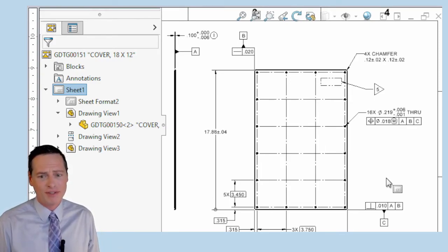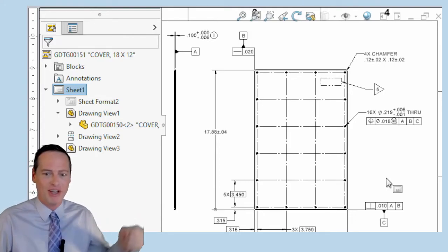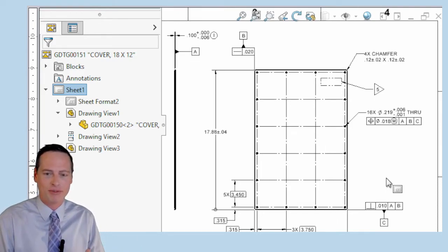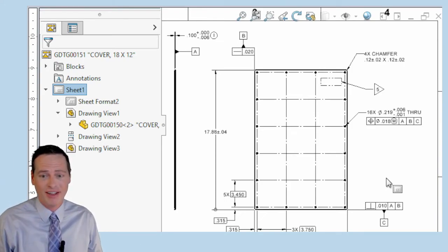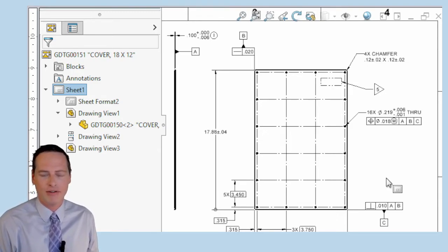This also asks a machinist to rough out the outer perimeter of the part, remove the part from the milling machine, put it back down on some other fixture where they simulate datum B and datum C, and then drill these holes in. A machinist probably doesn't want to do that. They probably just want to machine this whole part in one setup, all the outside and the holes, and that's going to make a better part for us. We wouldn't want them to do that and then have the part fail inspection just because of some silly thing having to do with the shifting of the holes in the pattern. Okay, and with regard to the edges of the part.